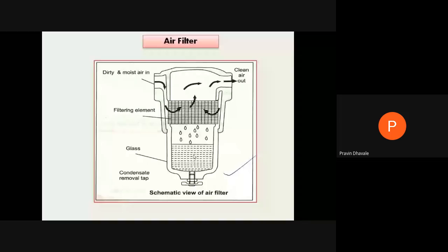will be stored at the bottom part of the air filter, and that condensate can be removed by using this tap. By opening this tap, we can remove the condensate from the air filter.